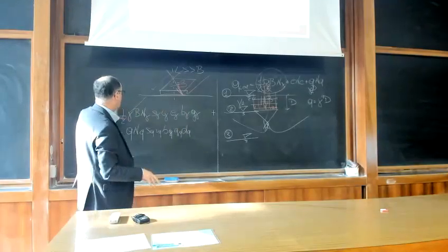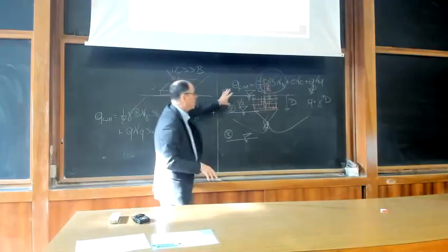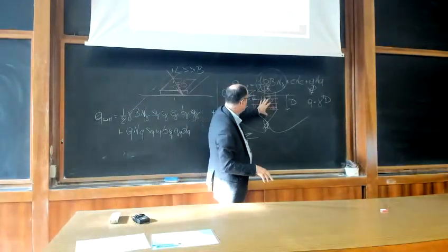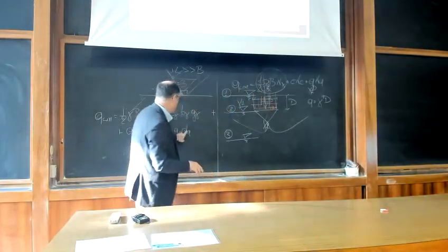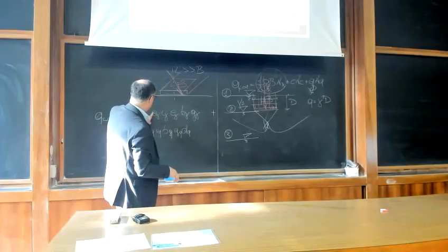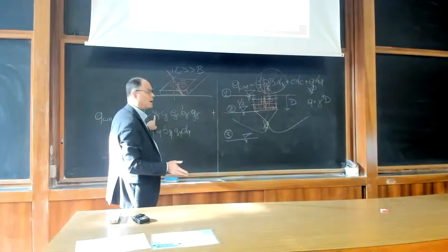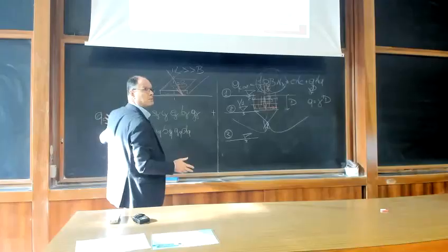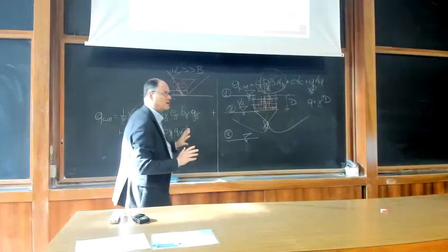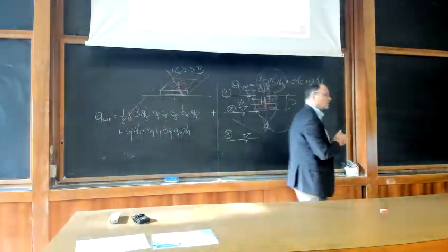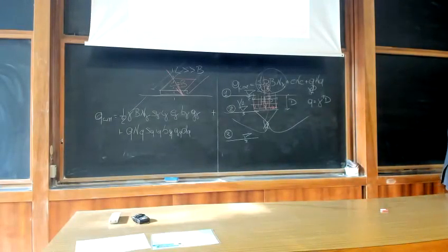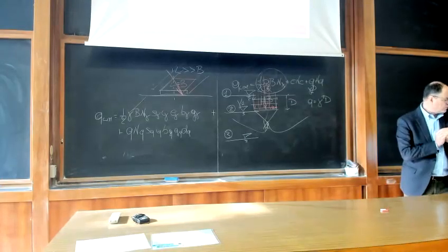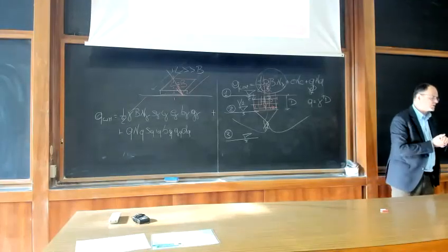They will tend to reduce the limit load, the limit pressure, when you have different conditions. So except for the depth factor and possibly some shape factors which can be greater than 1, all these will tend to reduce your limits in a way that at some stage you lose control.